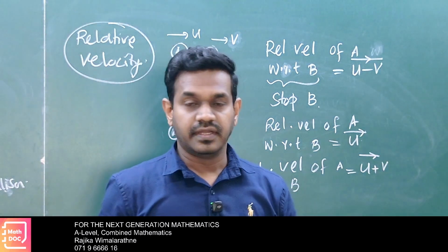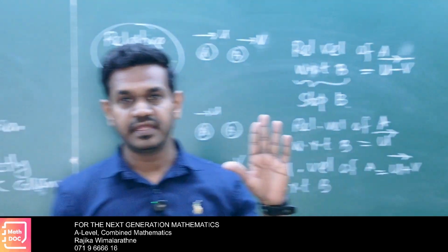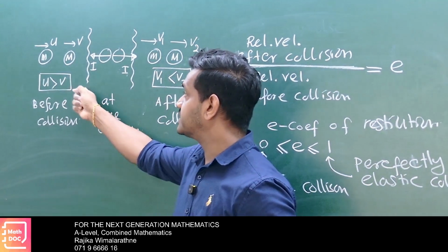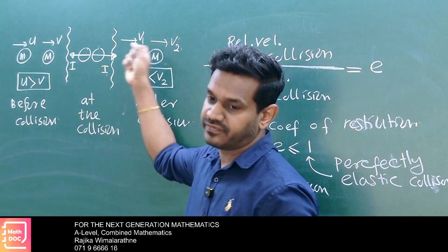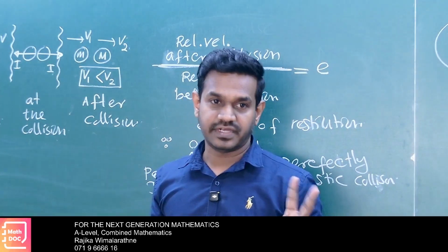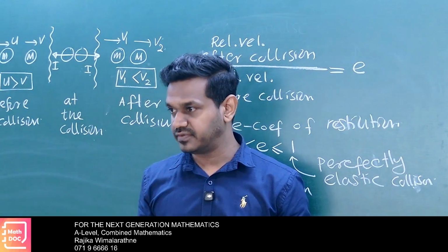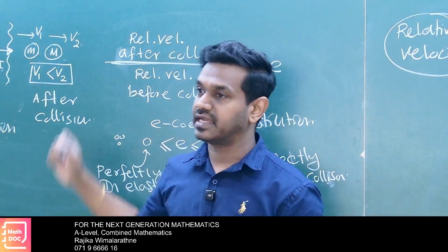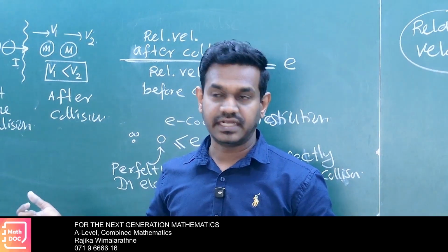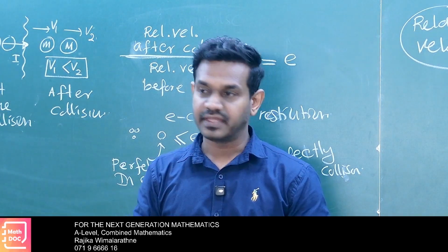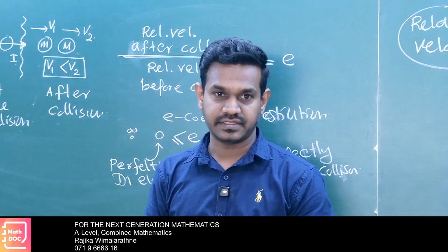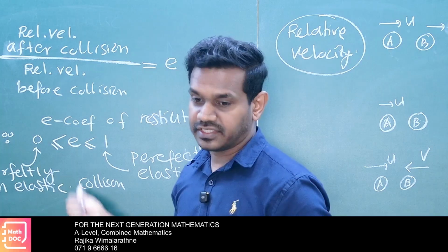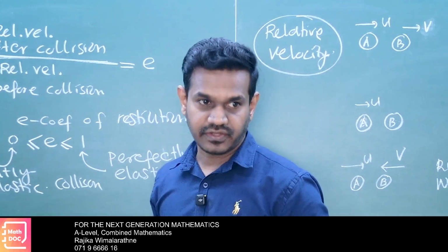Okay. Now you come to this one. Now here these two particles, after this collision, there are two different velocities now, v1 and v2. Then to find those two different velocities, we have two equations, no? So one is known, that is by conservation of momentum we can take that, or otherwise by considering I equal delta v we can derive conservation of momentum. Then finally we can get that equation. Then further we need another equation. So we take Newton's law of restitution.